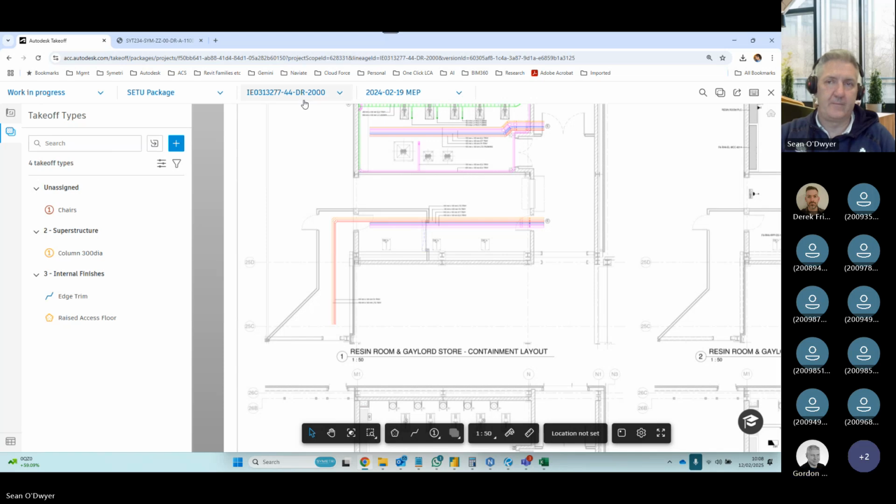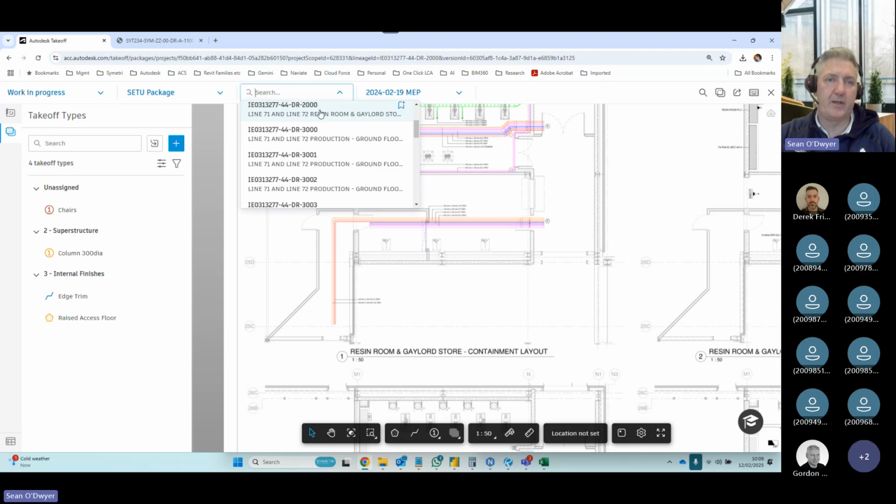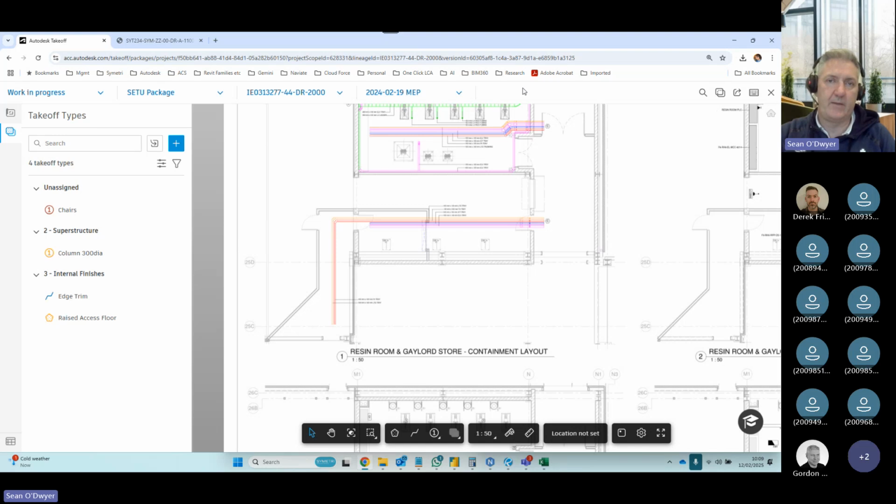Okay. But the packages, the different elements you're going to take off. Yeah. So you have one for electrics, you have one for ducting, you have one for curtain walling. Yeah, you can do that. You can break your packages into that, or you could have a package by date, and you can break your drawings, so you can filter it by your drawings, which would be your general services, your curtain walling, your finishes. So it is multiple ways of filtering these down and grouping it.